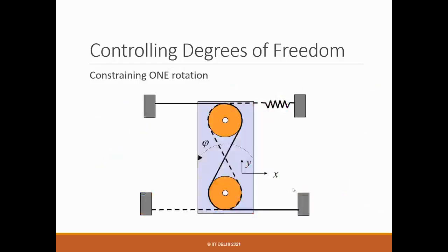You can also get it through cabling. Suppose you have these members, and you route the wire like this, and then another member. This side is basically for preloading, and at the end you provide this spring, so that you can adjust it and tune your preloading.